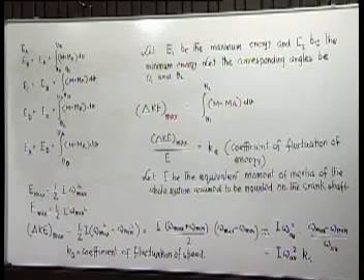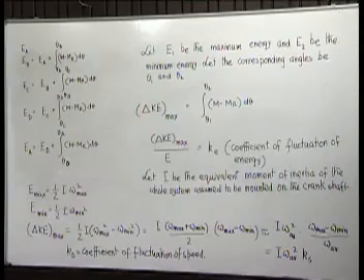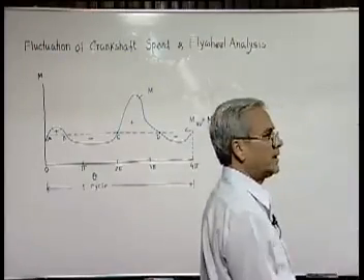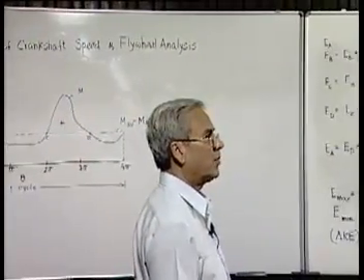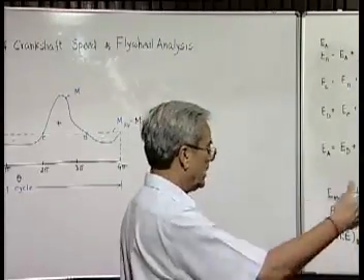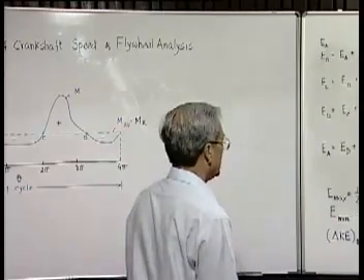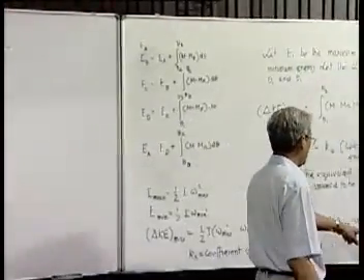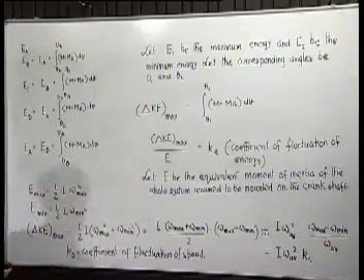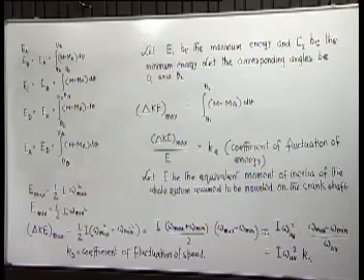How can it be done? The easiest way of doing it is that we attach a heavy wheel to the crankshaft. Normally that is called a flywheel because its function apparently is not seen very clearly, but what it does, it provides a substantial amount of magnitude to this moment of inertia attached to the crankshaft, and for a given fluctuation of energy it produces much less fluctuation in the speed, or in other words the engine runs smoothly.